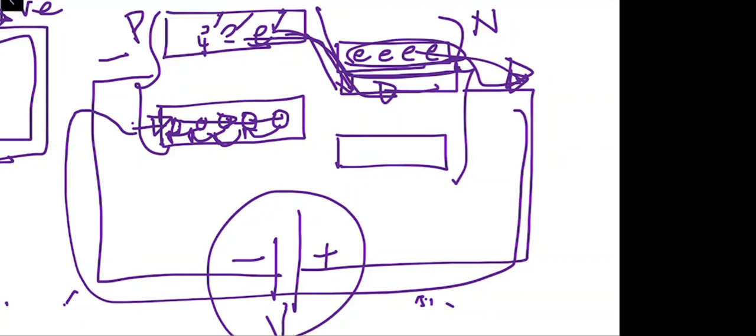So a chain reaction is going to start. If every electron gets 2 electrons from the valence band, this kind of reaction will start, and a very high amount of current will start flowing due to this very high voltage, right? So in case that happens, a kind of avalanche will occur.